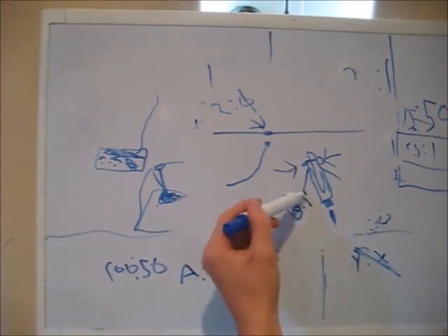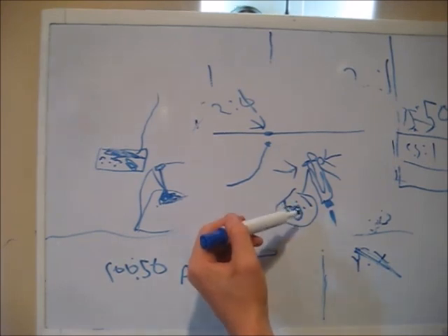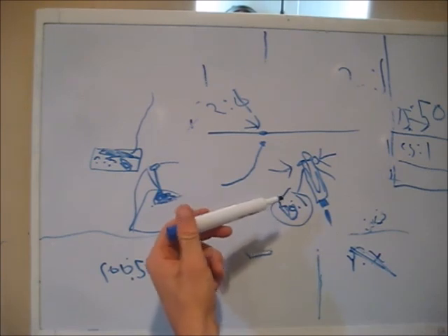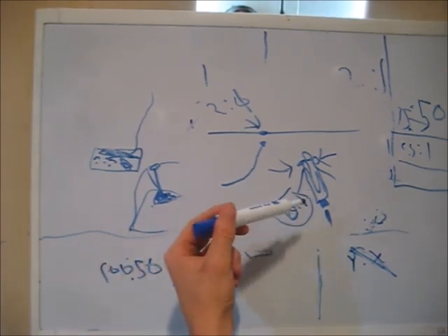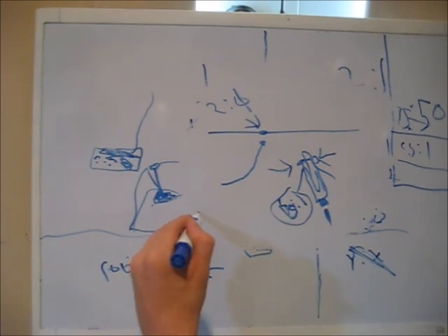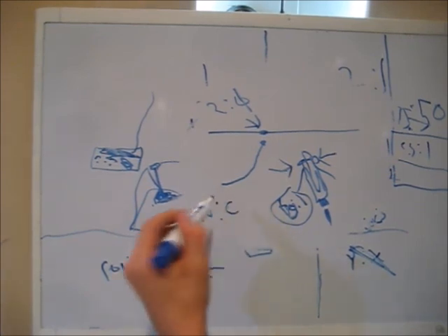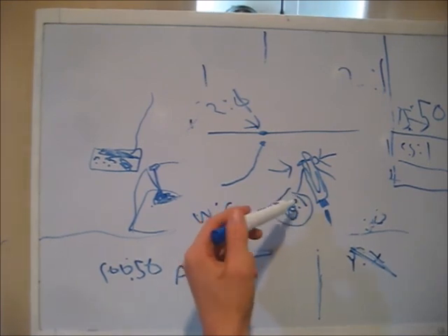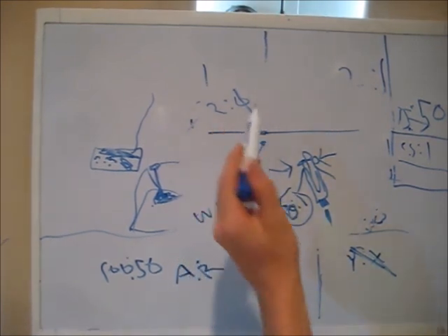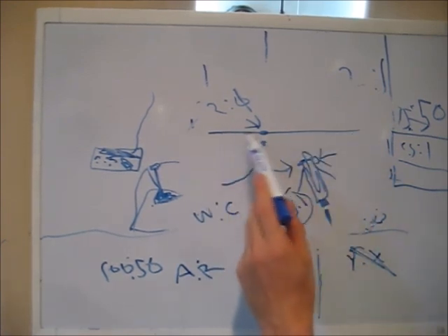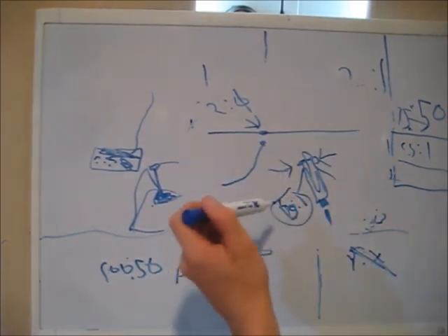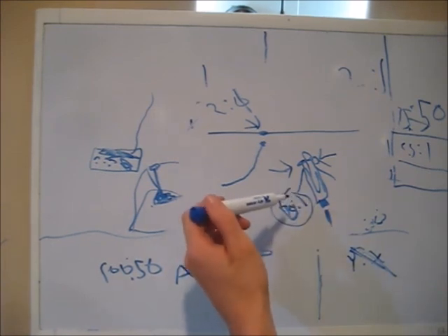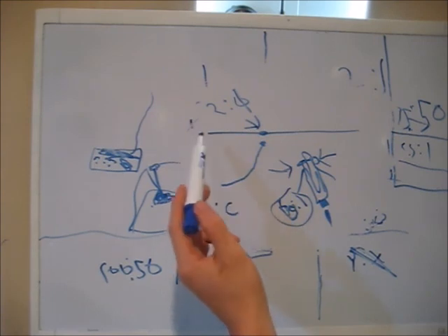So this is the exact same theory as the SWR, the antenna to radio factor, but now it's going to be rewritten as wire to coax factor. And you have to do this in your head. That is how they're rated. So if you have 75 ohms impedance and you want to make it 50, you'd get a 1.5-to-1 balun. So that doesn't mean that's what the SWR is that they're going to have. It just means that's what it's going to convert it to.